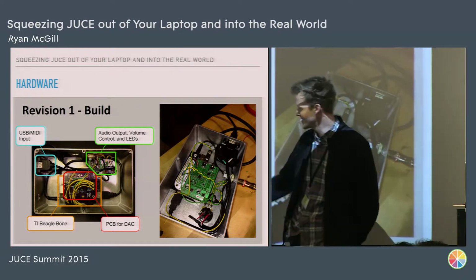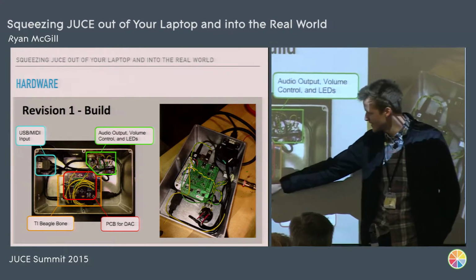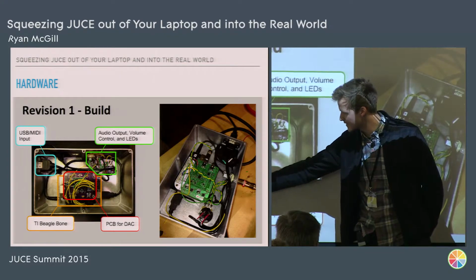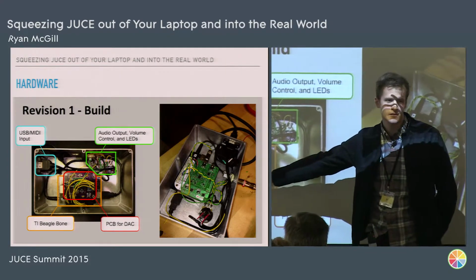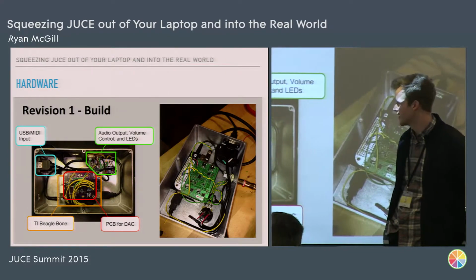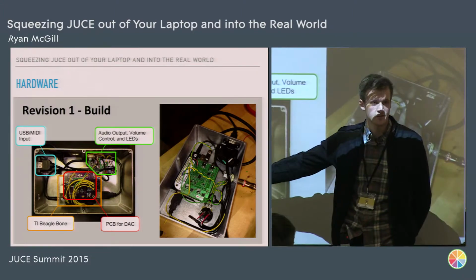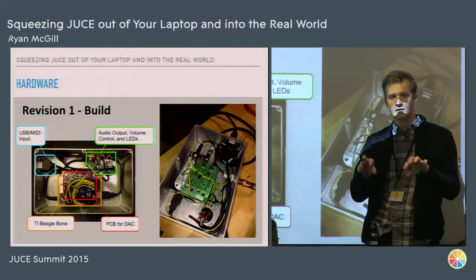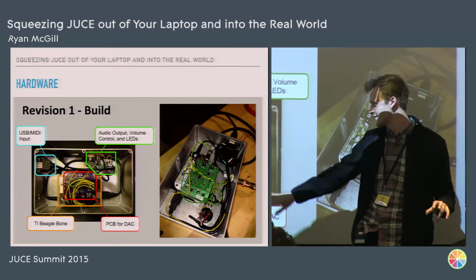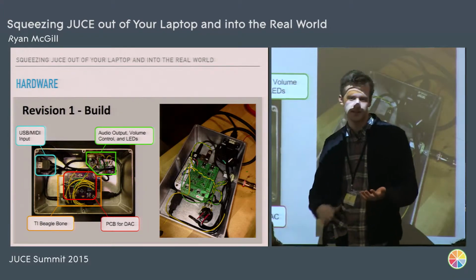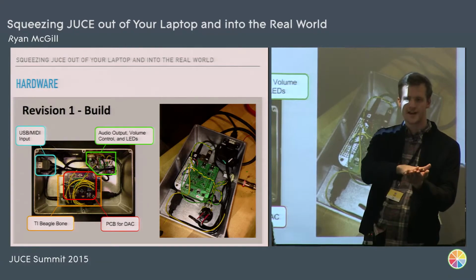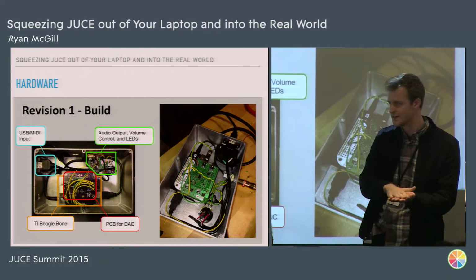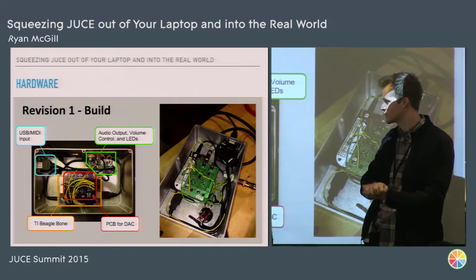And so then you just hook up. This looks really messy, but these are the 4 serial communication wires. Now, if you get one of those chips that I told you you should get, where you just Google Raspberry Pi I2S DAC, you don't have to worry about hooking up these cables because they're made in the form factor where they'll just plug and play. So that's probably a better option.